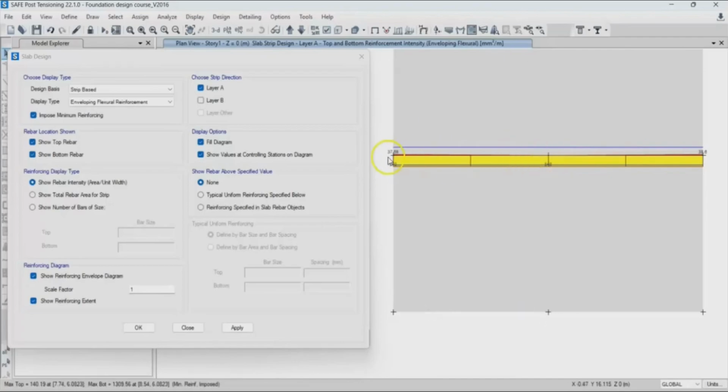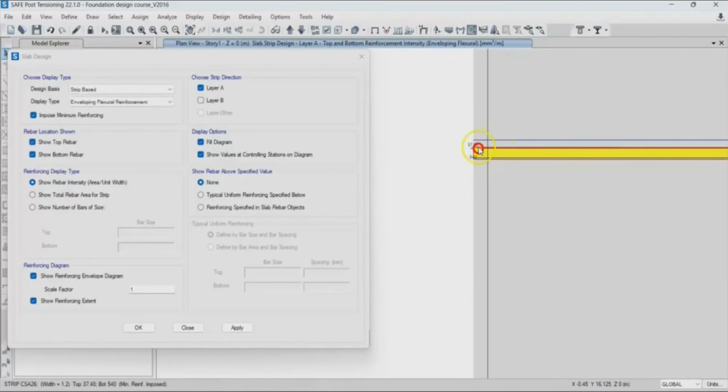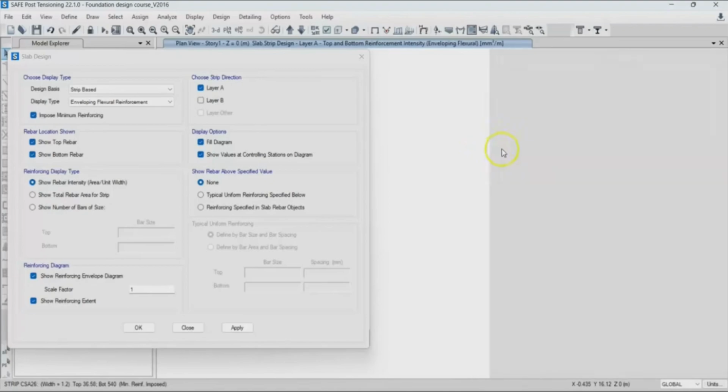Okay, so for this red, you can see this top part where we have the red color is almost invisible. You can't really see it, right? This happens because the edge of the footing can sometimes experience slight reverse curvature, or what we call localized stress. So for a normal standard isolated footing, these top values displayed in red color are usually so small that we can even ignore them, right? So the top steel is typically not provided for most isolated footings.